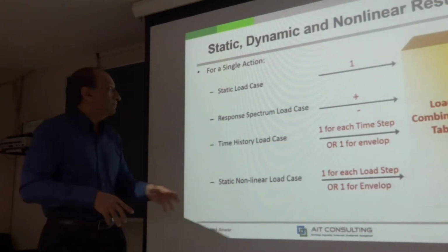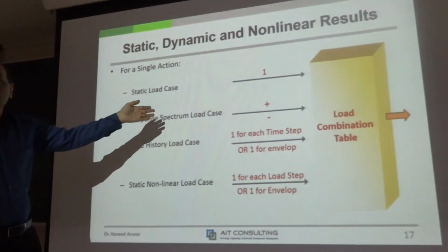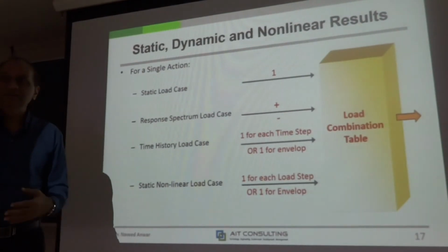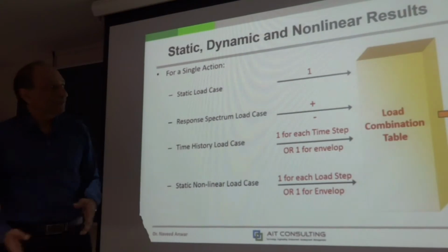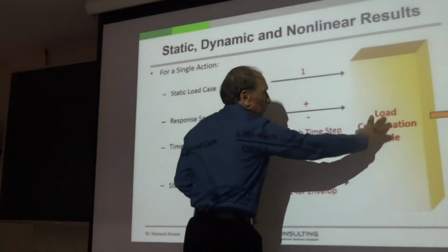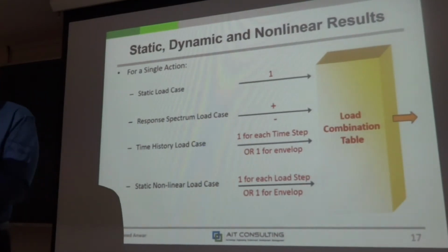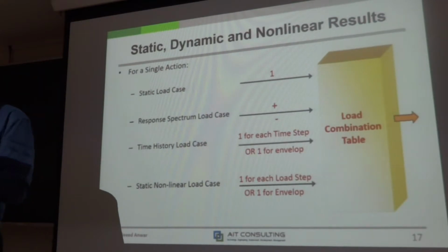Then they must be combined with dead load and live load, and any other combination of that. An earthquake in this direction, that direction, and others. So it obviously becomes a very large amount of data that will go to the load combination table. Sometimes for the program, it takes longer just to combine the results than to do the analysis.